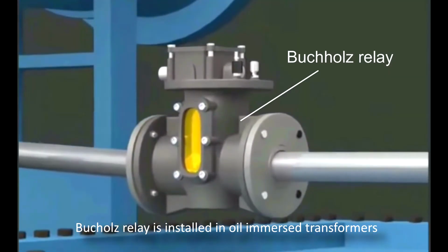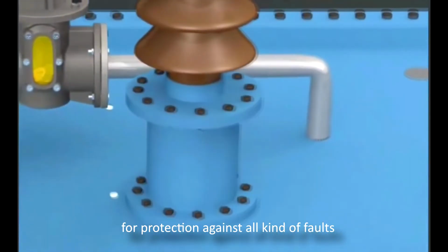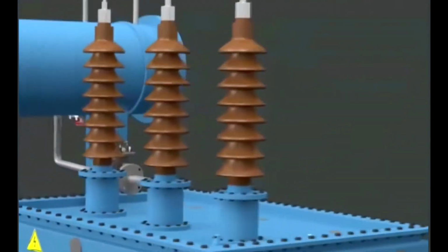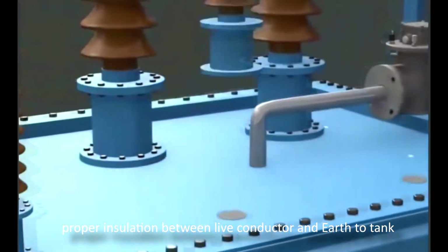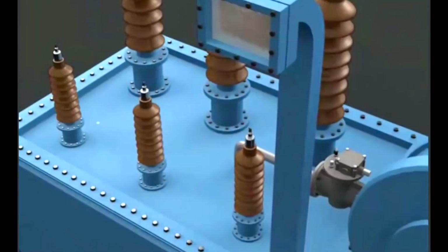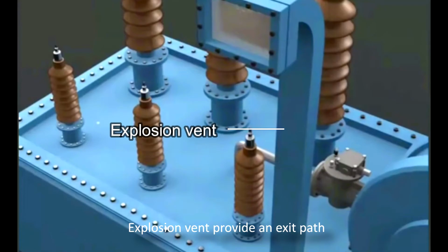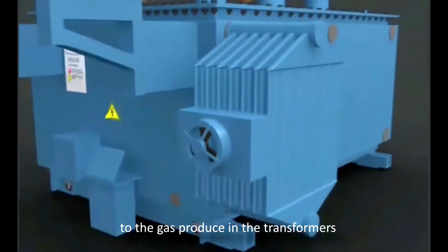The Buchholz relay is installed in oil immersed transformers for protection against all kinds of faults. The high and low voltage bushings provide proper insulation between the live conductor and earth to tank. The explosion vent provides an exit path for the gas produced in the transformer.